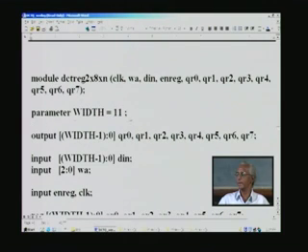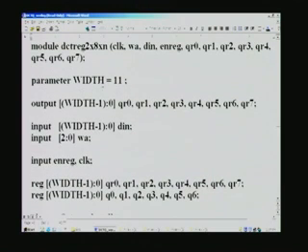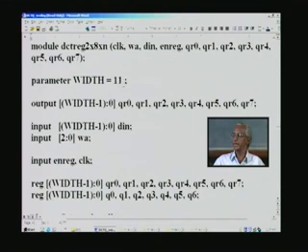And as I mentioned, n is a programmable thing, so you can do this by having a special C-like instruction here. We can declare any variable here and assign some known value. For example, width has been assigned 11 decimal here, by declaring it as a parameter, and once you declare this, instead of writing 11 at every point, we need to only write width here, and that is what we have seen. This is the output width, that is the register size here, and if you take 11 here, 11 minus 1 is 10, so 10 through 0, that is 11 bits for the QR registers.